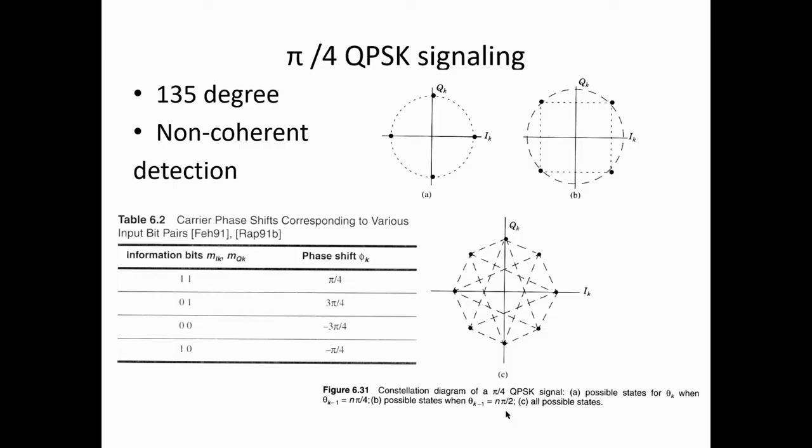The 180 degree phase shift creates a non-linearity. At the transmitter end, this non-linearity will create side lobes. To overcome this drawback, the phase shift has to be reduced. So in offset QPSK, we are reducing the phase shift from 180 degrees to 90 degrees by providing some delay.